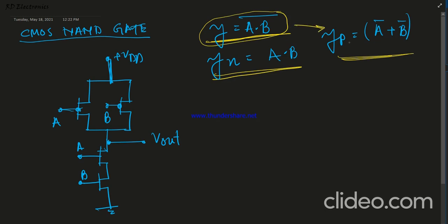So this is known as the PMOS equivalent network. y equals a dot b whole bar. That means if we apply De Morgan's here, then it is equal to a bar plus b bar. And the NMOS equivalent network is just the uncomplemented form, that means a dot b of this equation. We all know that variables in an AND combination mean the transistors are connected in series, and if variables are in an OR operation, then the transistors must be connected in a parallel combination. Okay, this is very important.